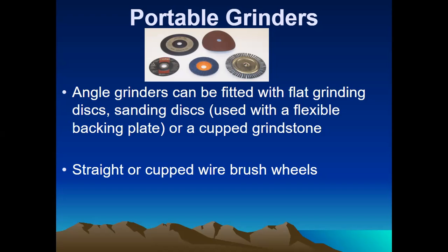And then on the right side of the screen on the bottom, we have a buffing wheel. Now, those are sometimes called a twist knot brush. And you get lots of these little wires, each one of those twisted little rope strands. It's probably got about 30 little steel wires in it. So they all get twisted up into these knots. That helps them not break as much, and basically helps us clean our material off nicer.